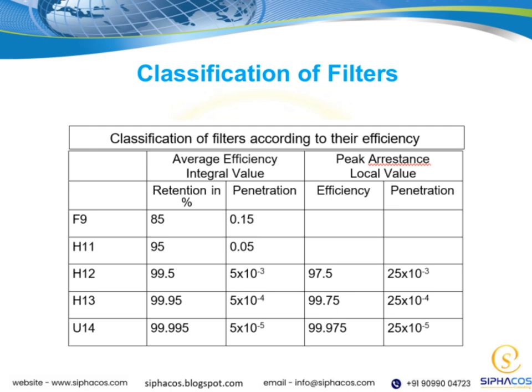Another important classification relates to their frequency response characteristics. Some filters are designed as low-pass, which means they allow signals below a certain cutoff frequency to pass through while attenuating higher frequencies. Conversely, high-pass filters do the opposite. They block low frequencies and let high frequencies through. Then there are bandpass filters, which only allow a specific range of frequencies, and bandstop filters, which block a particular band of frequencies.